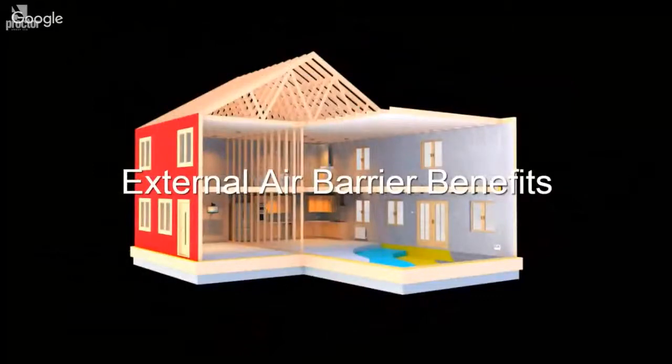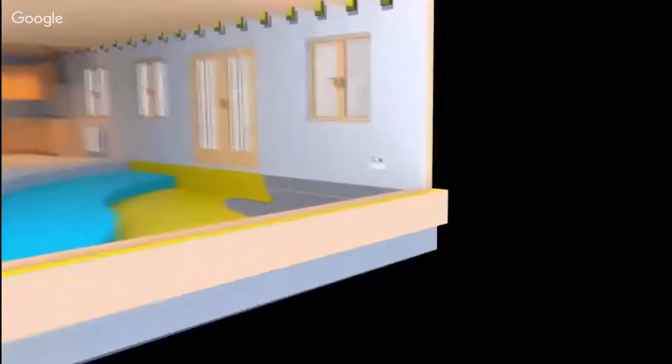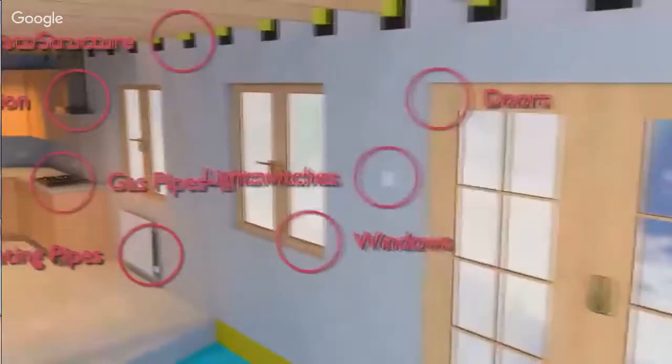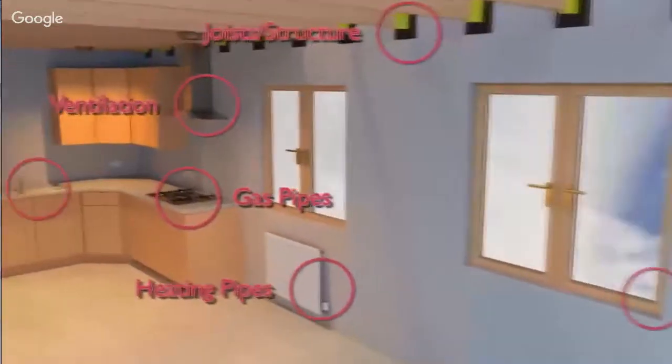The main benefits of an external air barrier come in the installation process and the robustness that it then adds when it's in situ. So if you have a look at internal air barriers, they require to be sealed around all surface penetrations, structural elements, and openings throughout the structure or the wall, which adds considerably to the time and cost of the installation process.